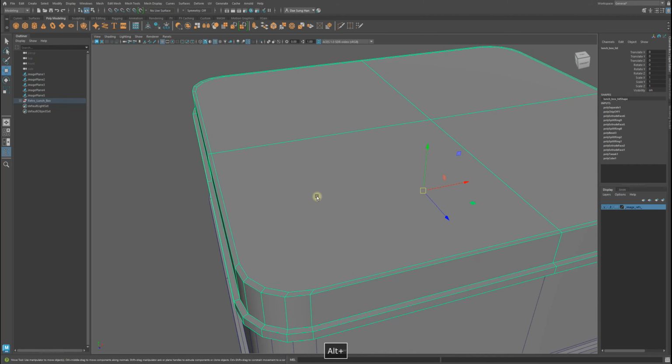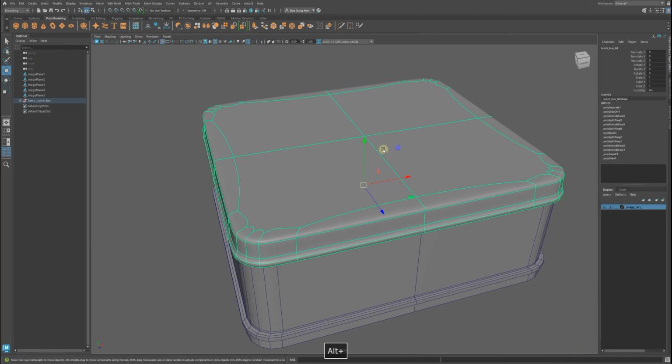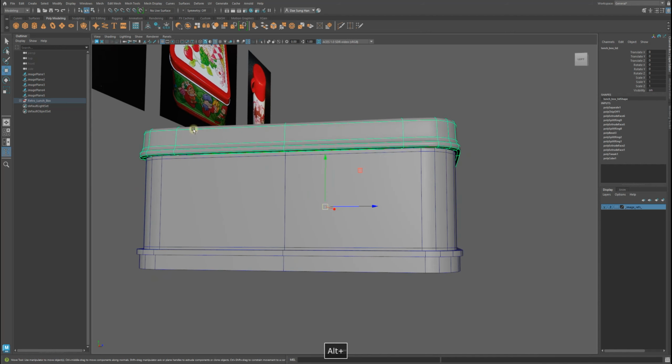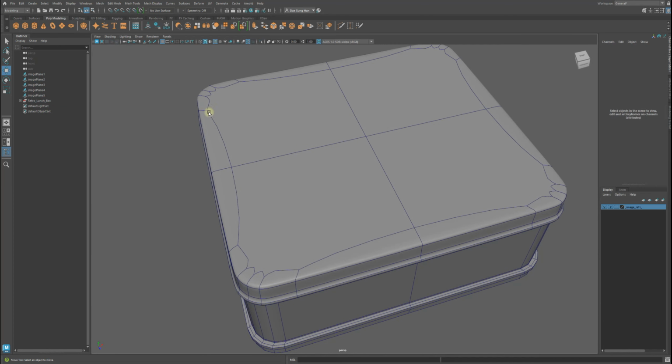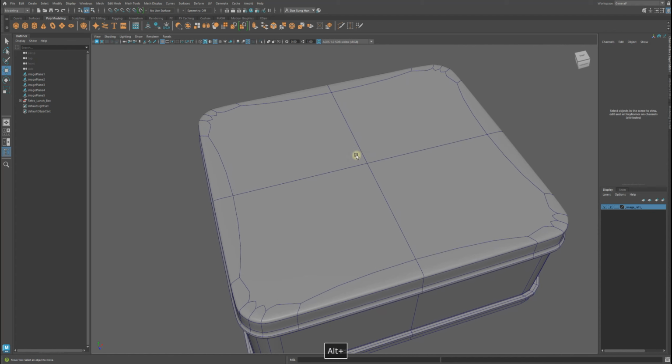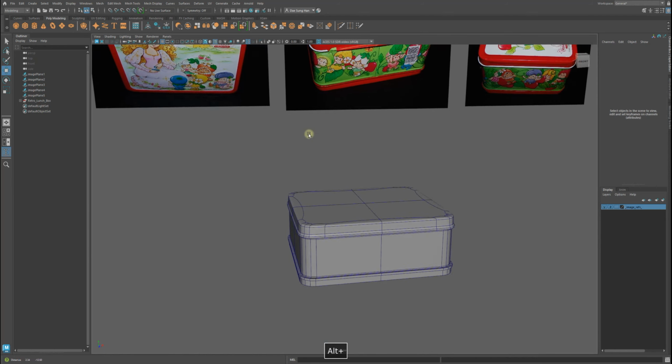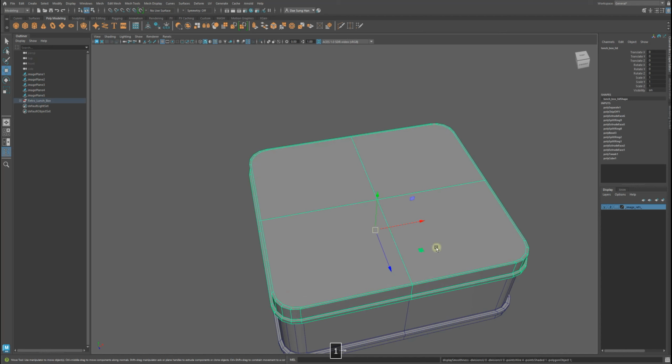Alright, so as you can see, when I press 3, which is the poly smooth, the smooth proxy, it does this. Let's say that I only add a color to it, but if I want to add, say for example, textures, I would need it to be sectioned off, to create lines in here that will make for good UV mapping, like a projection.